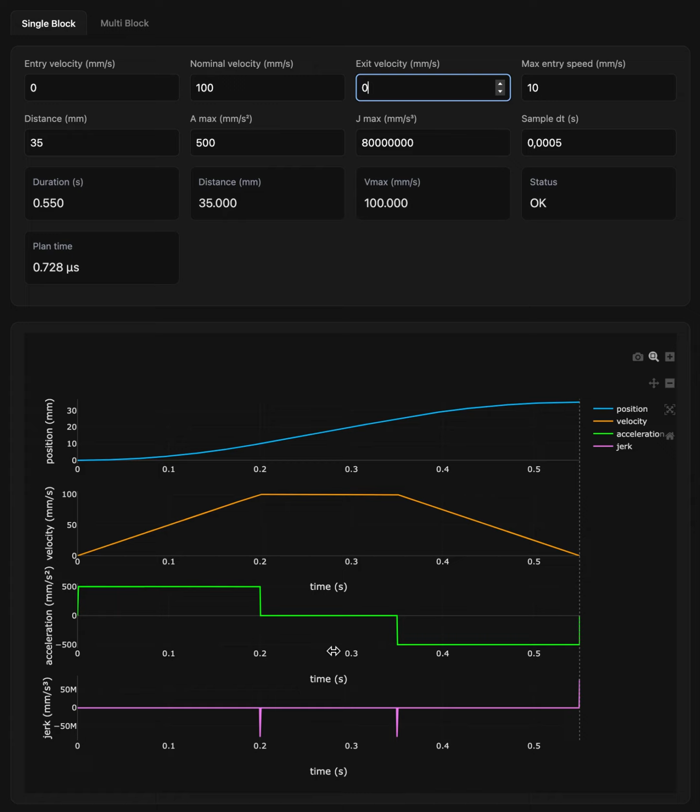Because the formula of linear advance has a term which is the derivative of extrusion times a constant, K. So when you calculate the rate of extrusion, you have what you plan to extrude plus a discontinuous function times a constant, and that makes the whole result a discontinuous extrusion rate.